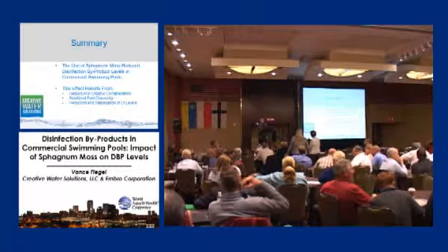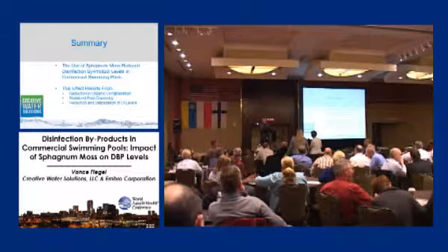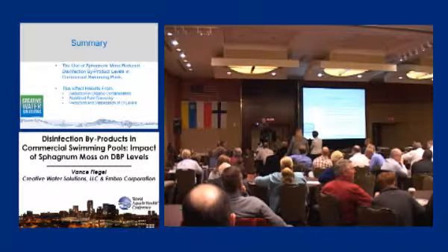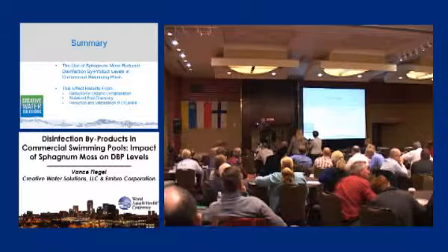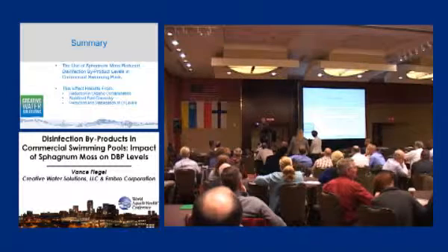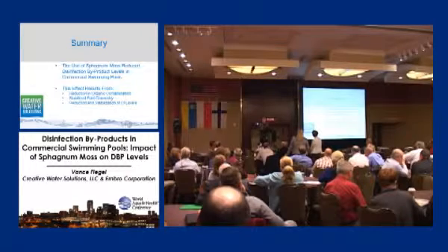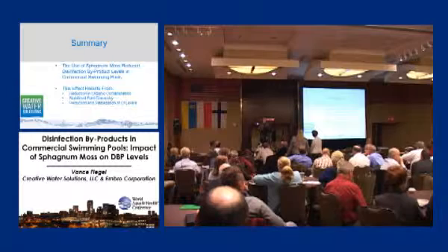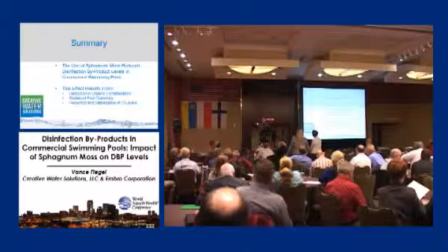So in these systems, did you replace the sand filter with the sphagnum moss? No. It's an add-on. We don't take anything off the pool systems whatsoever. So you have the sand filter, then the sphagnum moss. Correct. So somehow you're reducing the organic load from the sand filter. Right. The sphagnum moss has compounds in it that are released from the moss and reduce organic contamination. We've done those studies in the laboratory, and we've also correlated them to field studies where we've looked at the contamination in the sand filters and see that it is reduced. Okay, thanks. That's great.